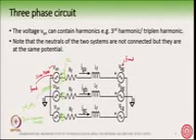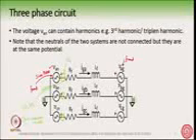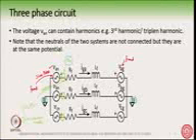Why can it not flow? Because this neutral here and this neutral here are completely isolated. Now you understand why these two neutrals are completely isolated, because of the third harmonics, etc. We are deliberately injecting that harmonic voltage, but there is no current flowing.